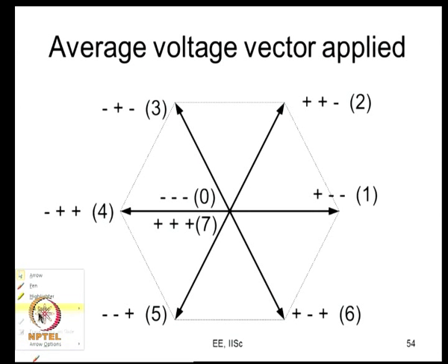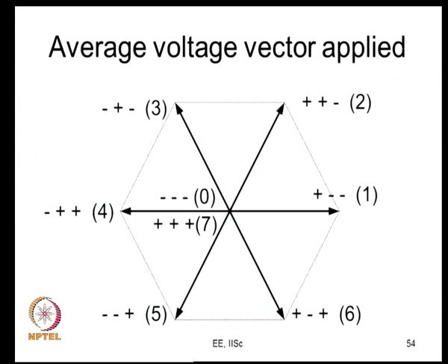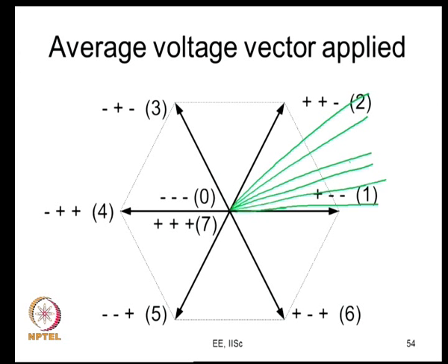Now, how are the vectors looking like? If you go to the earlier slide, the angle goes on changing linearly. So, what it does mean is in every angular step now, for example, this is the reference vector in the first one, this is the reference vector in the other one, these are all uniformly spaced is what it says. The reference vectors are still uniformly spaced, though I am not able to draw it as neatly.